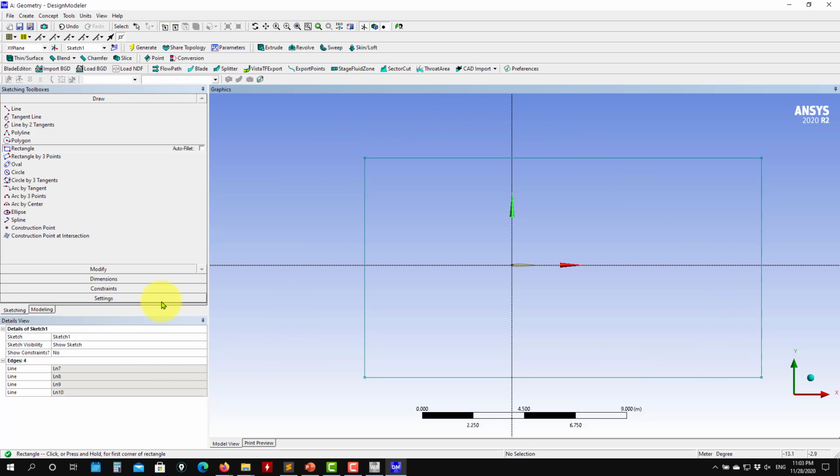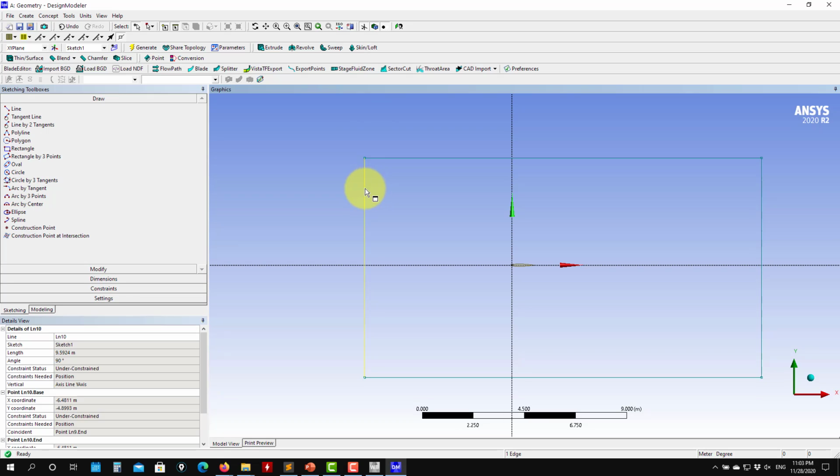So here you see what we're going to do in the CFD simulations. This will be a boundary, okay? So here we are going to have flow entering here, going out here, top and bottom walls or outlets, whatever, and then walls around the airfoil, okay? So now we need to give boundary conditions, something that we haven't done previously in potential methods. Now here we need to do it in CFD.